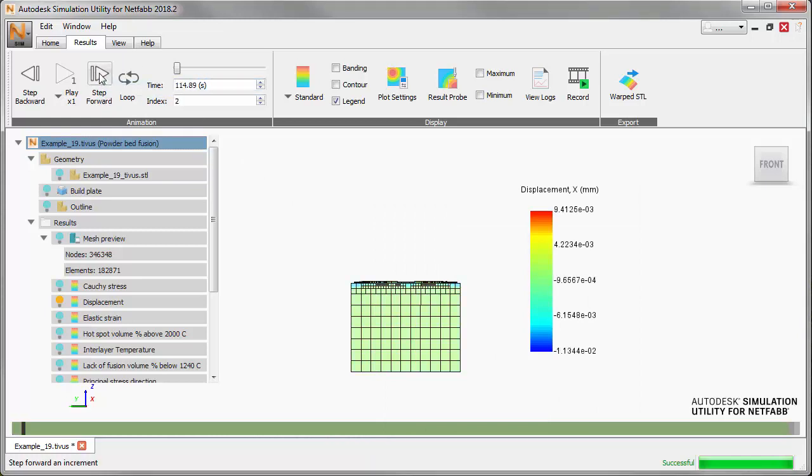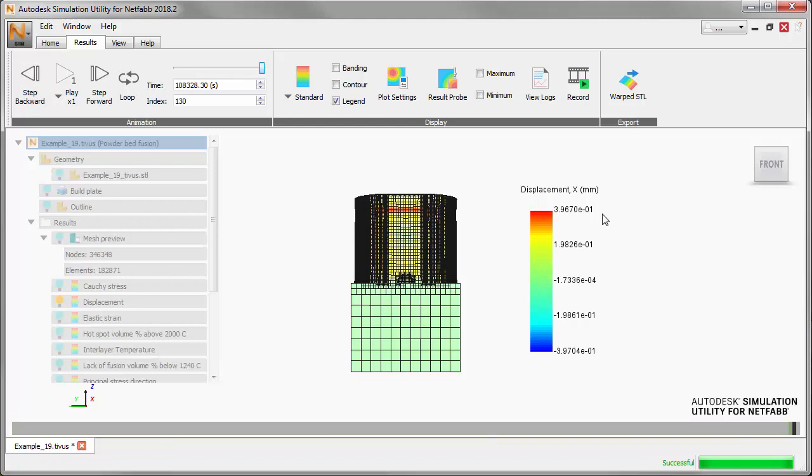Now when we find the peak displacement value, it is 0.39 millimeters, very close to the measured results of 0.40 millimeters. So this scaled PRM file appears ready to use in other simulations with Inconel 718, producing accurate predictions of displacement. If additional results are analyzed, it's possible to revise the scale factor for improved simulation accuracy.